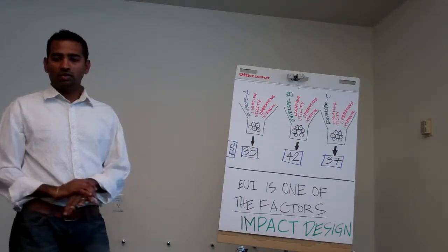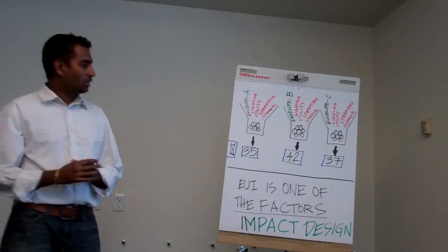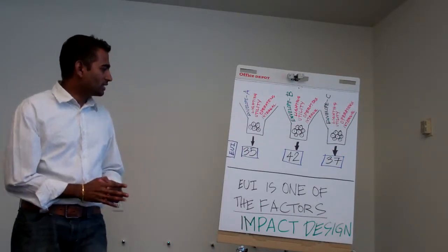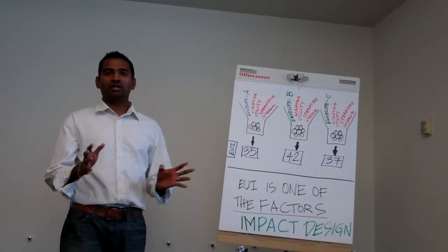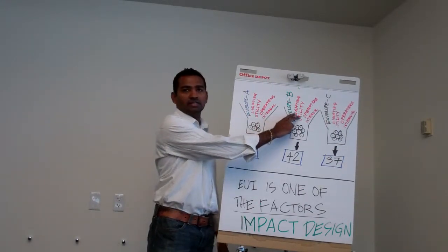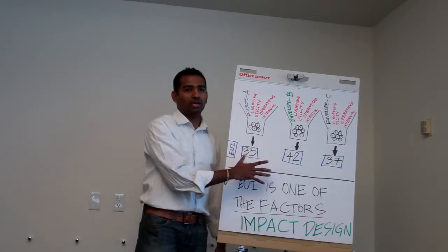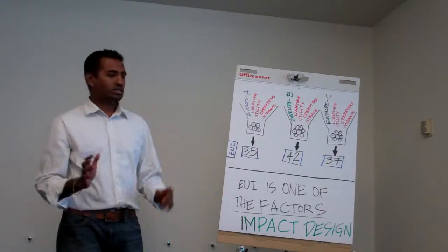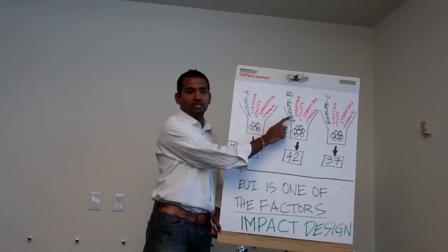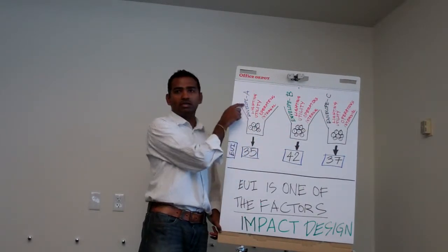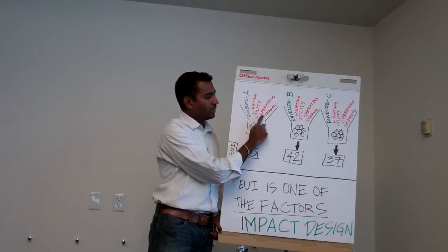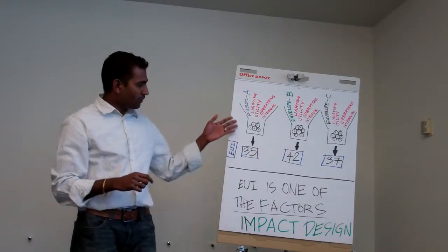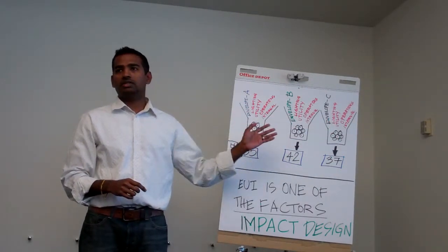So I know we probably don't have the time for the quiz today, but this is one of the important sheets for today's discussion. We talked about these different ingredients that go into this mix to find your EUI. The most important thing to understand in energy analysis is that, in order to find the best of one of these ingredients, you have to keep everything else the same. It's very important to do that. And you also have to keep the tool the same. You can't keep changing the tool, right?